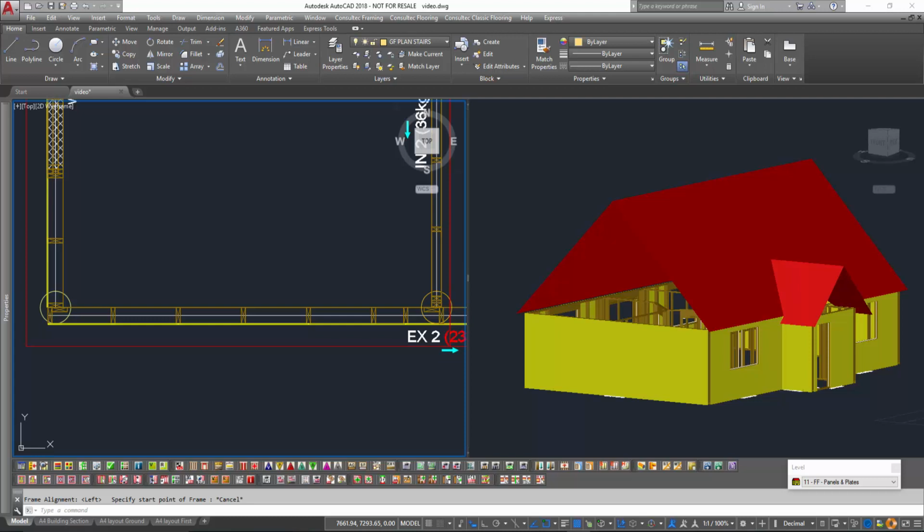Now that we have created our 3D roof, we now need to insert some gable panels. There are two ways we can do this. We can either draw rectangular panels and project them to the top of the rafter, or we can insert panels which are in the shape of a gable panel. If we choose to insert gable panels, then we will need to enter the correct pitch information into the options. In this demonstration, I'll show both examples.